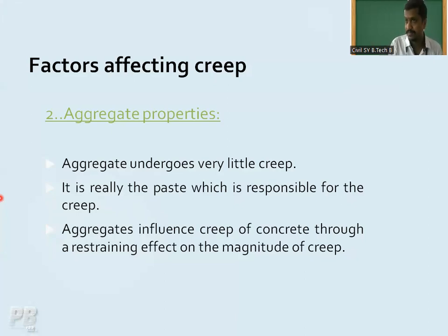So as our aggregates are tough enough to sustain the load, these aggregates undergo very little creep. It is really the paste, that is your rest matrix, like cement, fine aggregate, and water. This is the paste which is responsible for the creep.